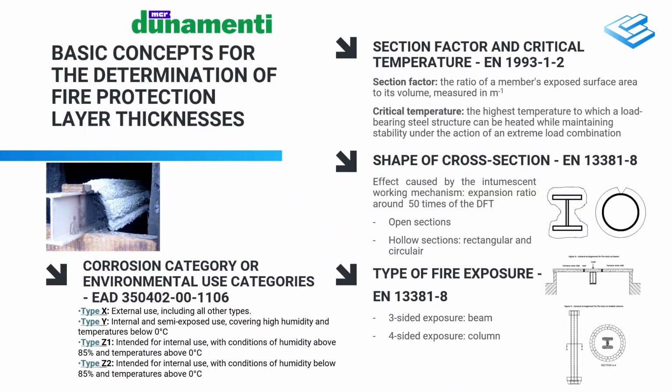Imagine the working mechanism: around 200 degrees Celsius, a carbon-based foam formation begins, resulting in an expansion ratio which is 50 times the original dry thickness, and it shows on the picture on the slide.